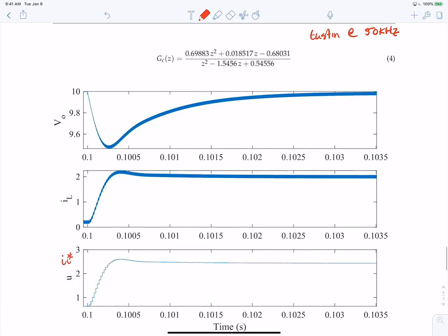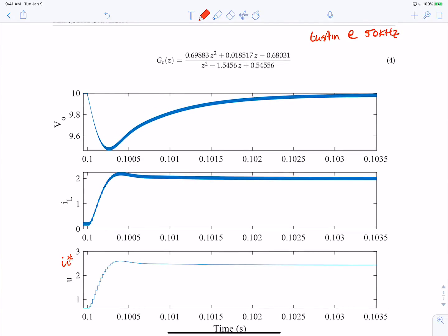You would get a slightly better one if you went up to 200 kilohertz, and you may be wondering, why don't I just do everything at the switching frequency? That's great. It depends. It depends quite a bit on cost and the application. So essentially, with all the other overhead with communication and the other things that your controller may have to do in terms of being a digital controller for power electronics, you may have a lot of overhead relegated to communication, right?